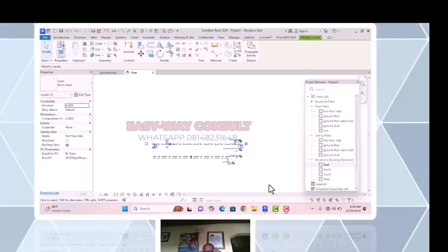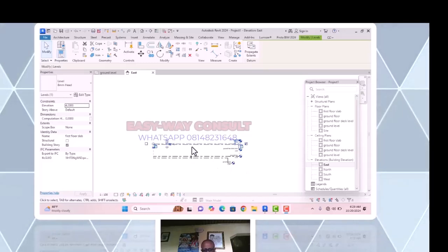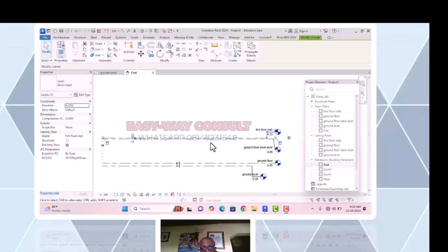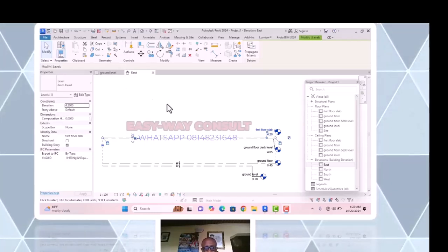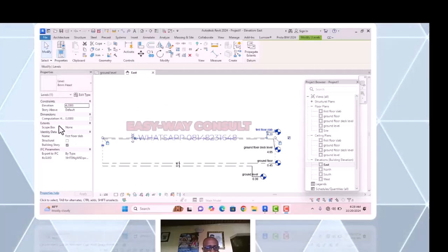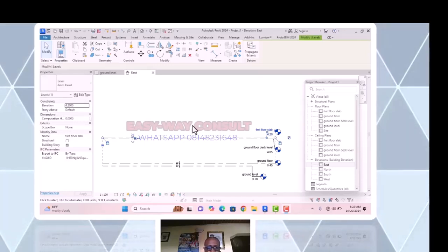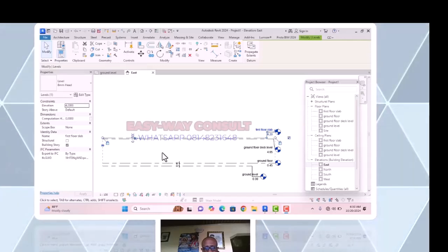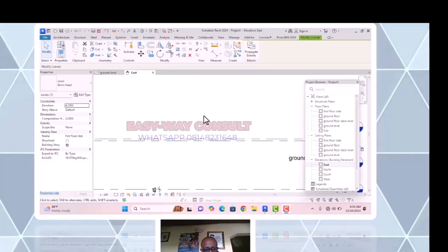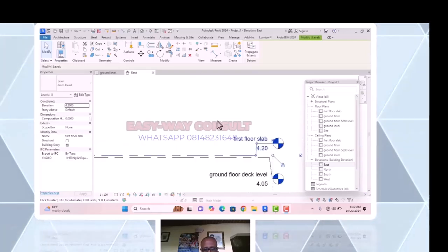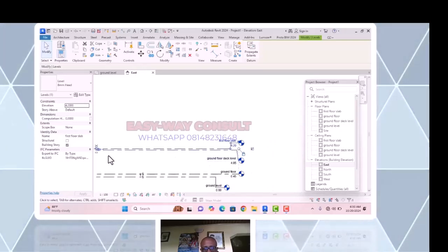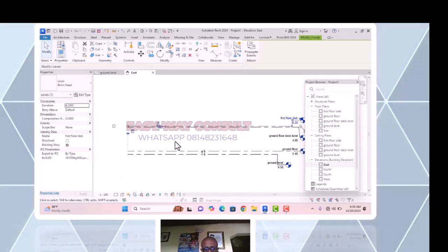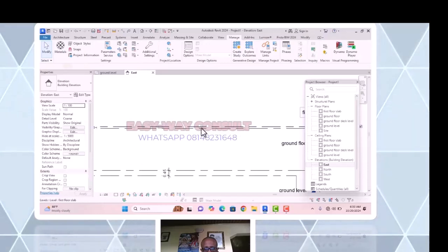So as you have gotten the slab right now, the next thing to do is you get another level. Some people may want to get the window level, lintel level, and the rest, but no. To make it very easy, when we get to that window and others, we will use these properties to get our measurement and also go to the 3D and others to adjust wherever we want to adjust. So right now you first of all exit this command. Remove the command, exit on it. Then you click to this. Exit.